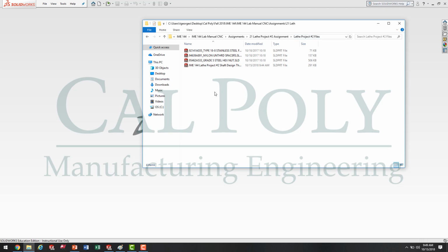File management is an important thing when dealing with assembly drawings and part drawings. If you don't keep all of your files in one location, the same location that you modeled them in, you might have to rename or reassociate the files when you reopen the assembly environment. So remember, if you don't want to have to do this, keep all of your files in one location and do not rename them after creating the assembly. If you do this, don't worry, I'll show you how to fix this in a later video.